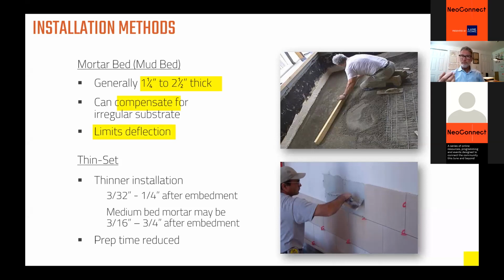It's expensive. Mortar bed methods are more expensive because they're more labor, and sometimes you have to depress your slab. Because of that, they're not used very often. They used to be, and mortar bed is still big on the West Coast. If you go to Europe, it's still big in Europe, and laying tile in mortar was always the traditional way to lay tile until 50 or 60 years ago, when thin set mortars came online.